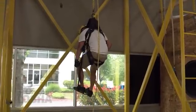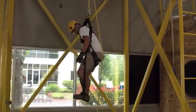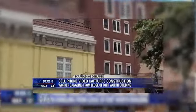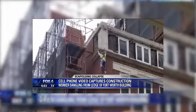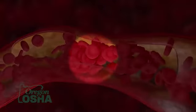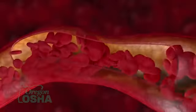If you do fall, you sit in that harness until somebody retrieves you. If somebody doesn't have a plan or doesn't know how to retrieve you, you could be sitting there for a while. If you're 200 feet off the ground, the fire department has to be called, they have to arrive, and you're going to wait there until they figure out how to reach you. You have minutes sitting in a harness, dangling there, with all the pressure on the inside of your thighs on the femoral artery, until you start to develop a clot. Whether a clot develops depends on if you have a blood disease, how healthy you are, and how much trauma you had when you fell. So those straps are extremely important.